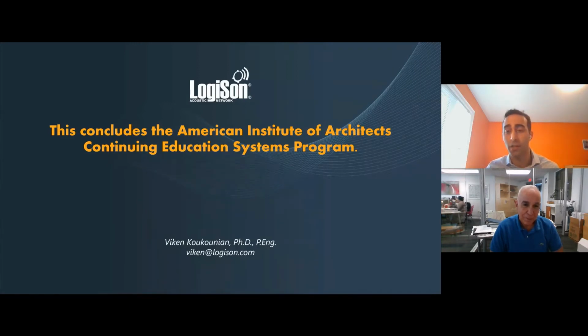That's an excellent question. It's for that very reason that many standards like GBI and WELL have structured their criteria in very unique ways. For example, the typical approach, which GBI, USGBC with the Green Globes document and LEED approach it, is by having separate sets of requirements for new construction and existing buildings, whereas the WELL standard is more conceptually effective at a high level. And so you can always approach the topic of acoustics at any period of time, but it's also best to get in front of it as much as possible. So when you're starting to lay things out, think about the acoustical expectations you have for these environments. What degree of privacy are you hoping for? And then you can situate the different types of spaces with their functions accordingly.